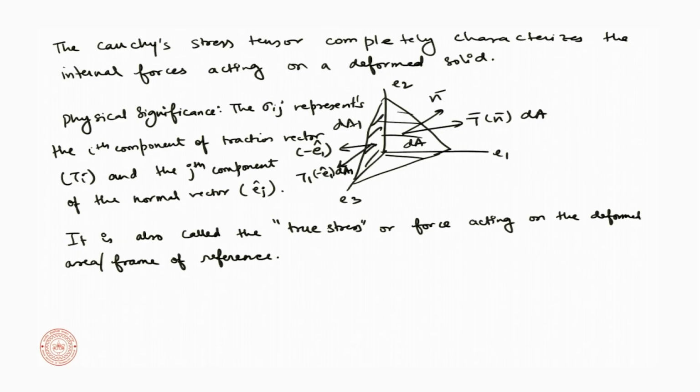All right. Apart from this, we will have 3 other definitions of stresses or 3 other stress tensors which come of use. The Cauchy stress tensor is actual force, just as a reminder, per unit actual or deformed area.